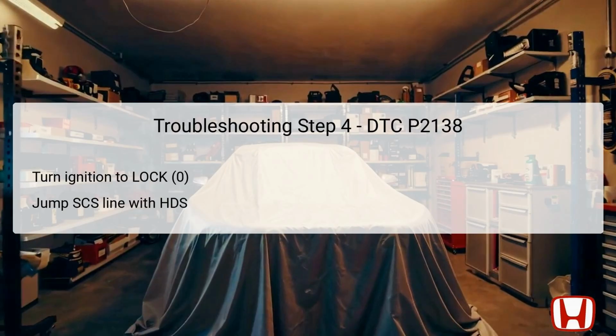Now turn the ignition switch to the lock, 0 position to ensure that all systems are powered down safely. At this point, you need to jump the SCS, Service Check Socket, line using the HDS, which allows for a special testing procedure for certain Honda vehicles. Jumping the SCS line enables diagnostic modes that can activate various components without starting the vehicle, providing a safe environment to test the connections and sensors.